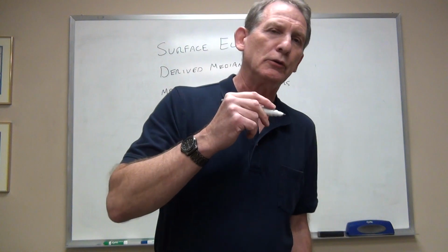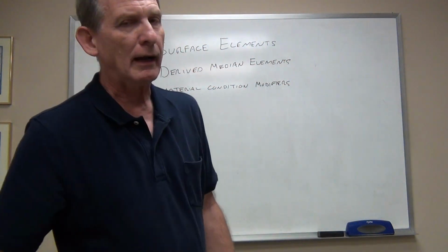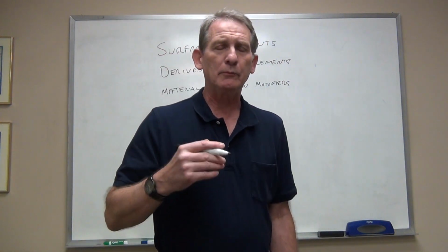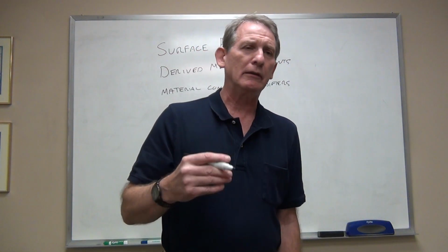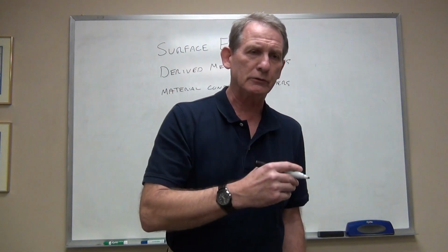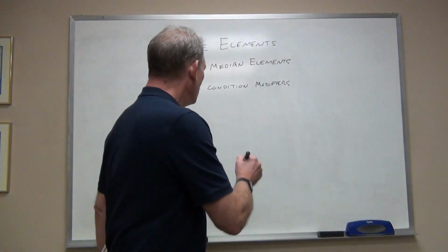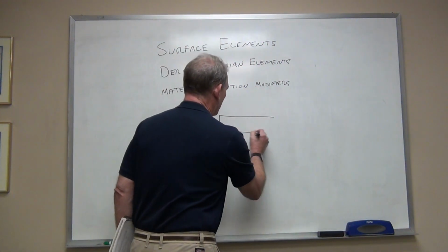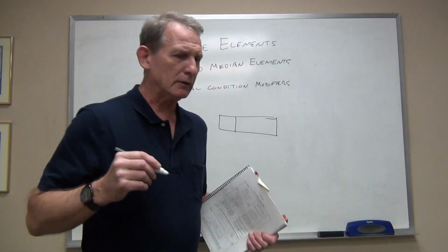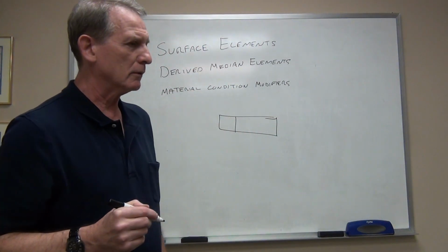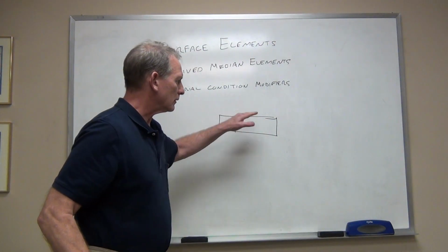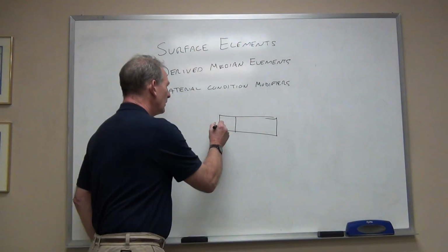Later on, when we get to using those additional little square blocks that go on the back end of the feature control frame, which are datum blocks, we're going to actually see that material condition modifier used there also, or potentially used there. But right now we're working strictly with the very simple form version of the feature control frame, just a symbol and a tolerance zone block information.